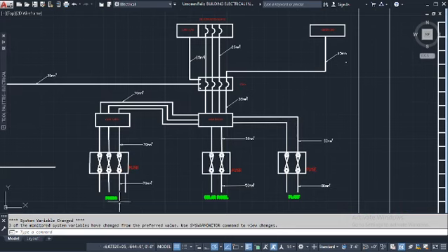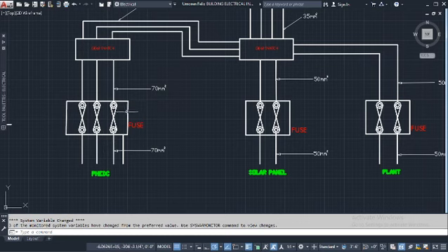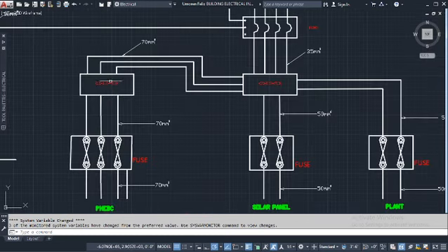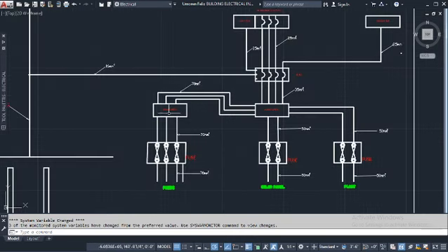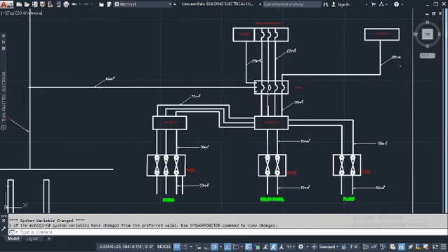What we are seeing here is the wires going from the sources down to the fuse. You can see our fuse here. From the fuse, it goes to the changeover switch. A changeover switch is connected to another changeover switch here. Since we have three power sources, unlike the former one where we had two sources, it is connected to the changeover switch. This one connects down. Then this changeover switch takes it to the RCBO.